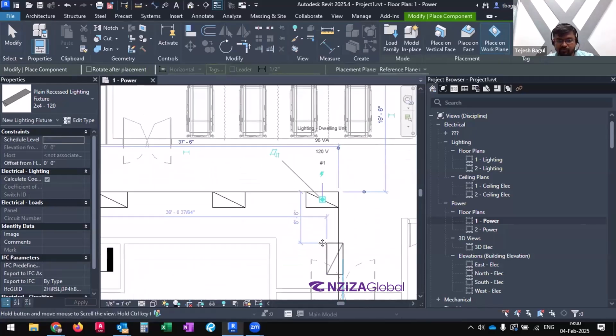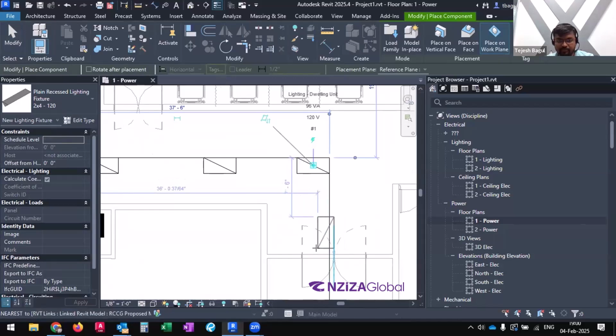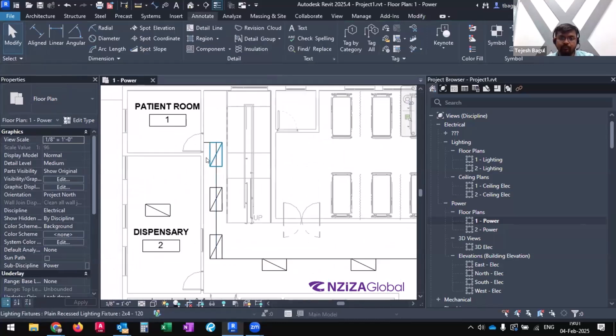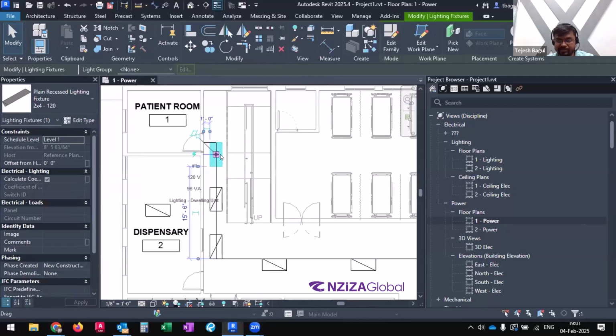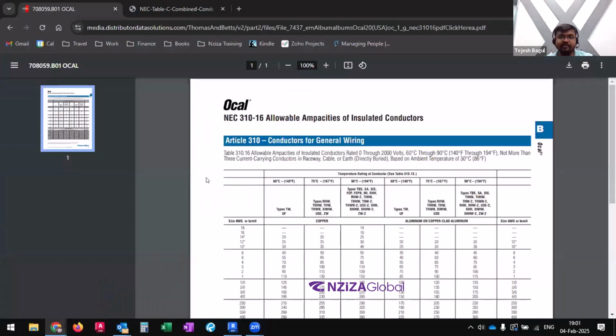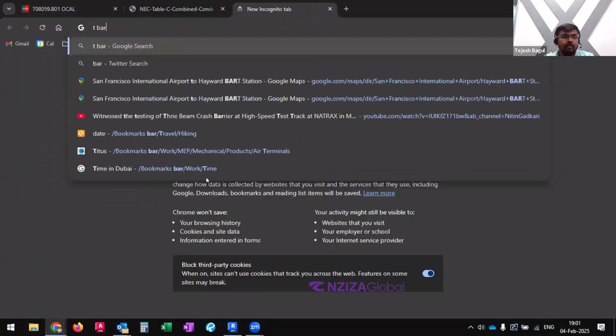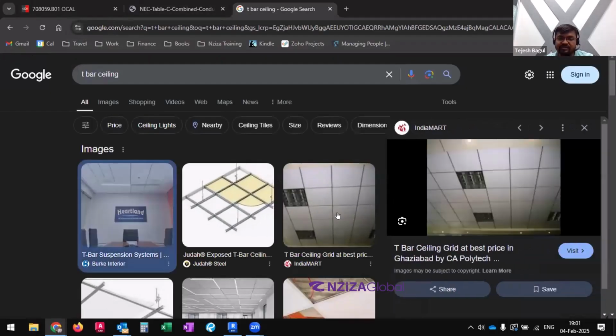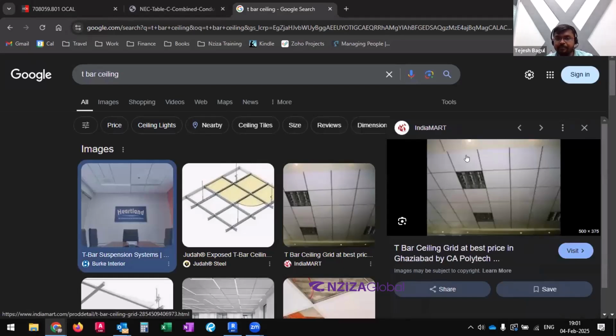And the last point that I was making before I noticed that my screen was not visible on Revit is that we will place these light fixtures in ceiling grids, like ceiling tiles or a T-bar ceiling. Last week we checked what the T-bar ceiling looks like, the ceiling grid over here, right? The troffers that we are placing right now look something like this. The ceiling grid will come in from the architect's model, okay? But as we know, in the real world, we might not be getting the latest architectural model right away.